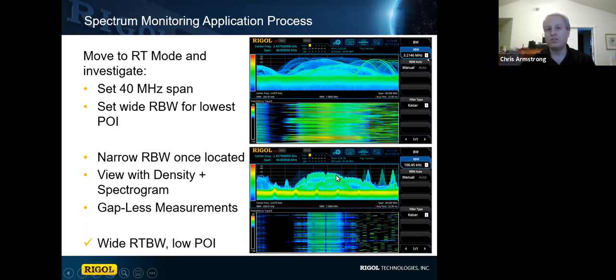Or once you find what you're looking for, once you measure it, you can zoom in with tighter RBW, which gives you a little more fluctuation in power levels outside the specifications, but gives you a broader or a better look at the individual signals, right? So we can now see, hey, here's a Wi-Fi signal in the 2.4 gig channel, and these little peaks here are Bluetooth access connections, some Bluetooth device, probably a mouse or something, testing different channels to optimize its path.